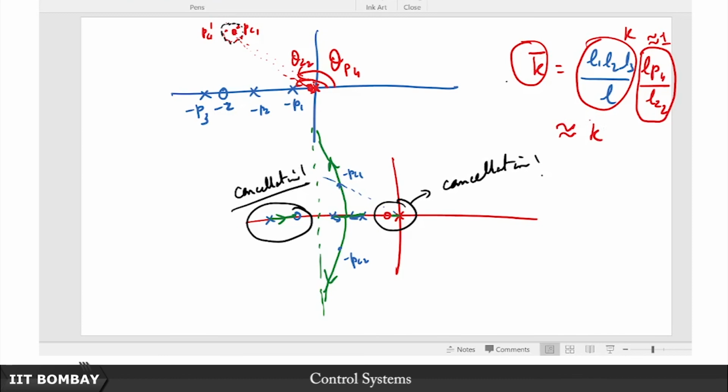this value of k bar that you attain at this point, at that value of k bar, this branch is not sensitive enough. In other words, this closed loop pole starting from k equal to 0 here has not migrated sufficiently close to this 0. Then you still have this pole 0 pair to contend with. This makes your system deviate from the ideal second order system assumption that you've made, and therefore even if you think that the dominant poles are here, in reality your dominant poles are not there.